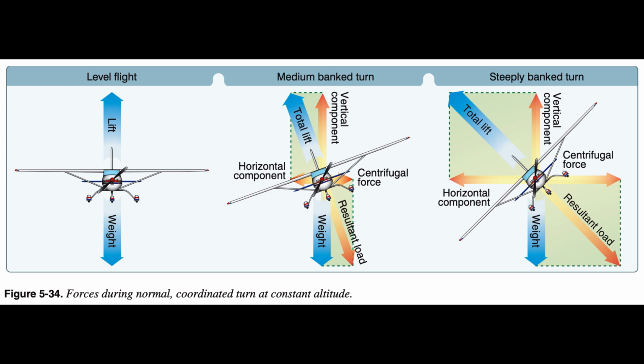Conversely, when an aircraft is banked, it turns provided it is not slipping to the inside of the turn. Good directional control is based on the fact that the aircraft attempts to turn whenever it is banked. Pilots should keep this fact in mind when attempting to hold the aircraft in straight and level flight. Merely banking the aircraft into a turn produces no change in the total amount of lift developed. Since the lift during the bank is divided into vertical and horizontal components, the amount of lift opposing gravity in supporting the aircraft's weight is reduced. Consequently, the aircraft loses altitude unless additional lift is created.